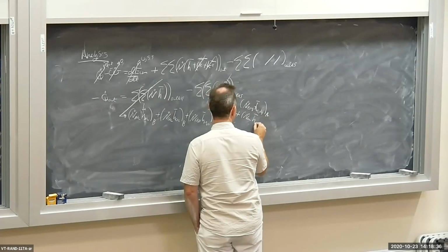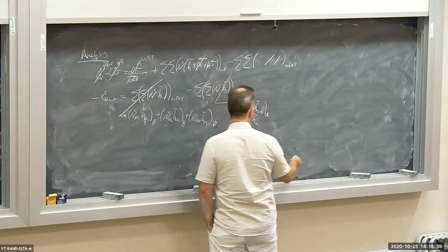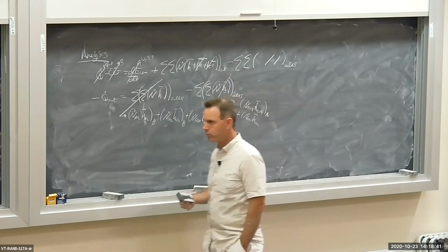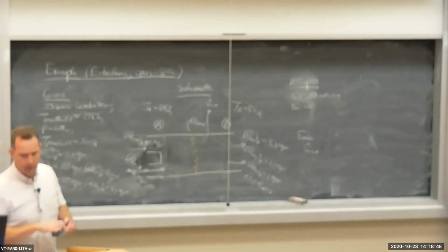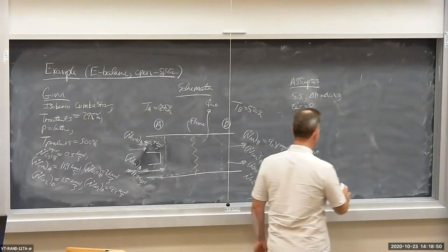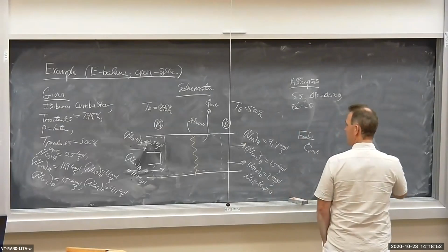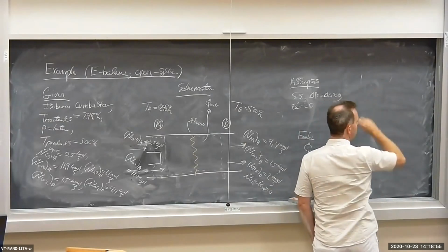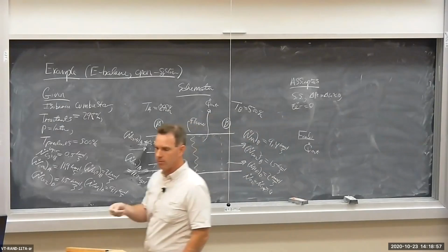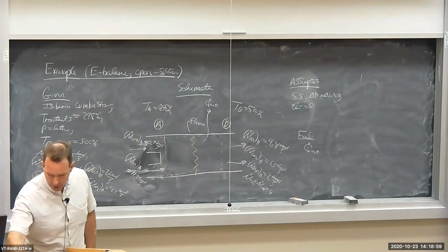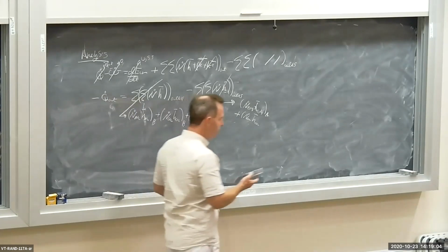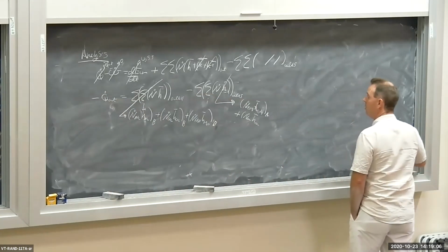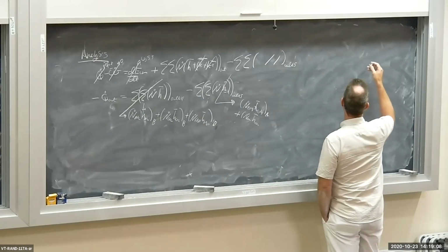H bar air. Now I'm going to be a little bit careful here. The air is composed of nitrogen and oxygen. So let's be real careful here. I'm going to write this in terms of the mole flow rates and the specific enthalpies for the oxygen and the nitrogen separately.